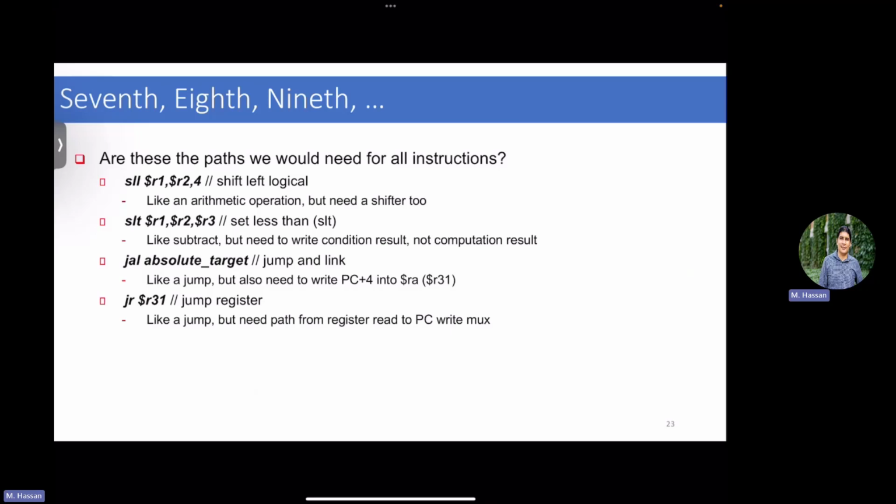Here in your data memory write enable, when should this be 1? There's only one instruction that writes to the memory, yeah? Store instruction. Anything else, this is just ignored. Now, picking up that path from the memory and updating it to the register file, there is a mux here. This mux is for when there's only one instruction reading from the memory, which is the load, right? So this one will take that path if it's a load, otherwise any other instruction will take from the ALU output. Good. And all this mess here is related to branching. If you have a branch, this is the 0 flag, and then if this is a jump. Good.